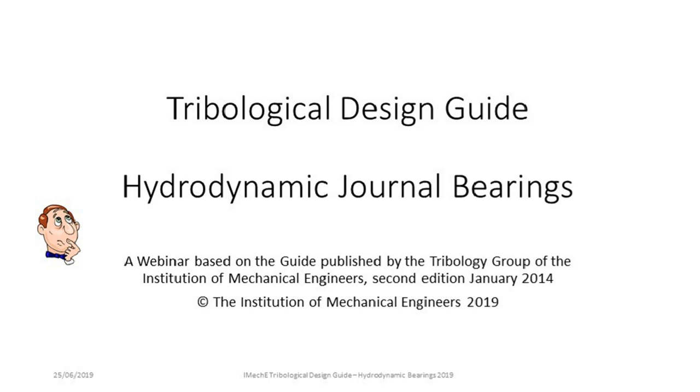Internal combustion engines can use hydrodynamic bearings because if you think of the torque speed characteristic, that builds up and has a similar sort of shape to the load carrying capacity of a hydrodynamic bearing. So the two are kind of matched. Whereas, as I say, the torque speed characteristic of an electric motor is pretty flat, or possibly descending. So as we move from internal combustion engines to electric propulsion, we're going to see more rolling element bearings.